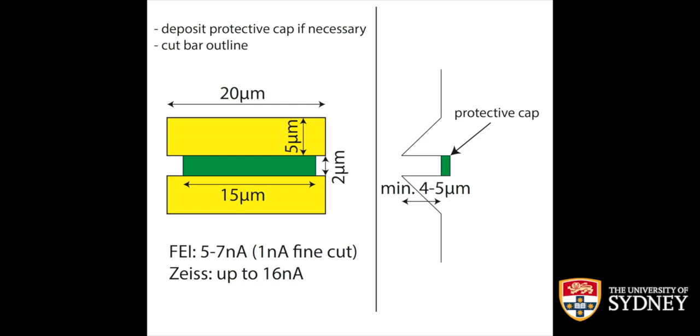So there's a variety of choices out there. There seems to be an agreement that sputtered deposited nickel gives pretty good results. In my opinion, platinum is okay. Platinum, trimethyl platinum, whatever is in a gas injection system in your FIB is a pretty good choice if you fully remove it. If you can't fully remove it because you need to have a look at the very surface,